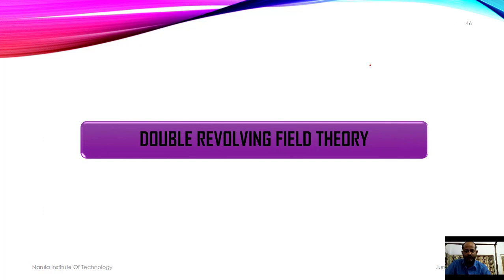Okay, so we have also mentioned, when we discussed in our lecture number 1 the working principle of single phase induction motor, that double revolving field theory is based on the idea that the air gap flux of single phase induction motor consists of 2 oppositely rotating magnetic fields in equal magnitudes, which rotate at synchronous speed, right?